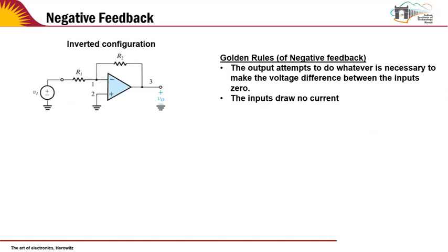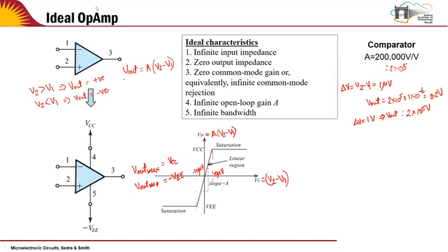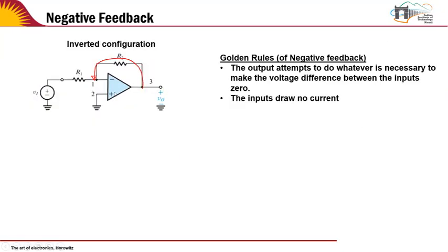Now, if you want to come up with new functionalities with the op amp, there are various ways to do it. The first thing is you have to go to a closed loop system. That means the output is now connected to the input terminal. Okay, so that is a closed loop system. Earlier it was an open loop system, which means there is no connection between the output and the input. So let's see what's the advantage of using a closed loop system.